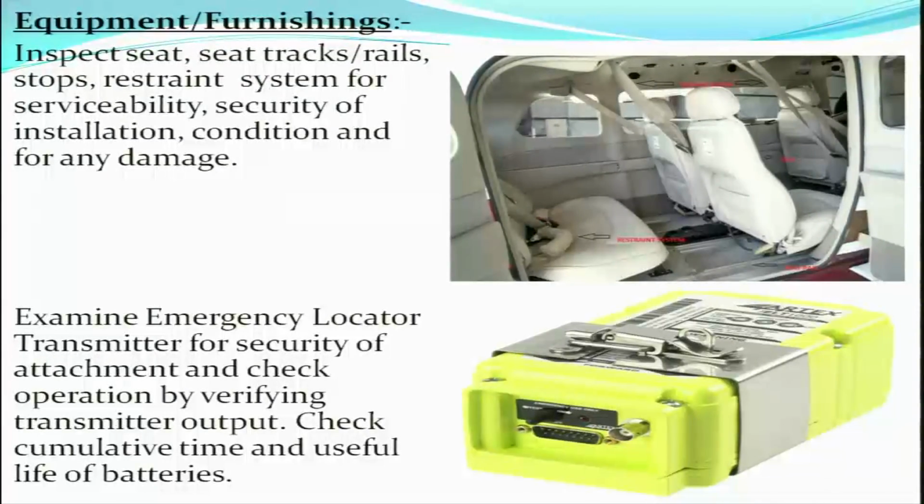So as part of the 100-hour schedule, we will also check that the ELT is securely attached. We will check the transmitter output. We will also check the cumulative time and the useful life of the ELT batteries.